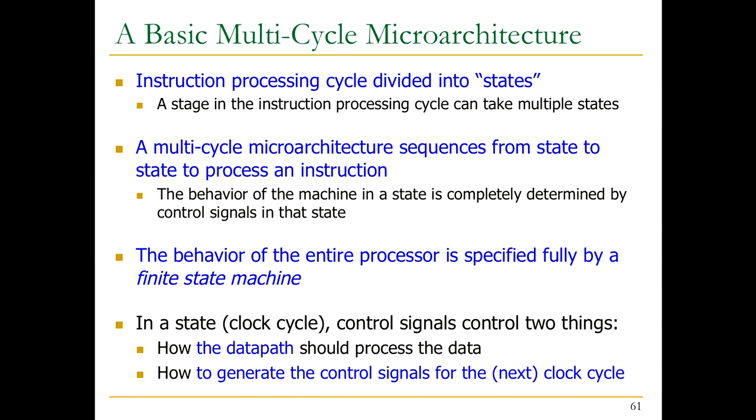I'm a big proponent of generating control signals as early as possible, of course, without wasting resources, because that's one principle that minimizes the potential of your critical path extending. If you generate your control signals earlier in a previous clock cycle, by definition, you're hopefully eliminating the possibility of extending your current clock cycle due to the generation of those signals.